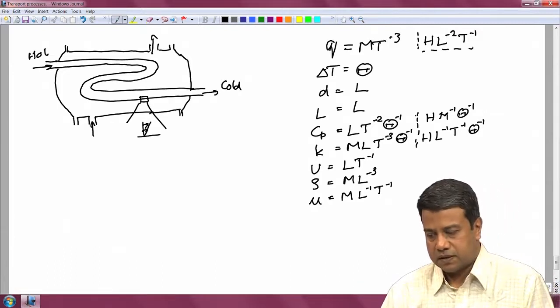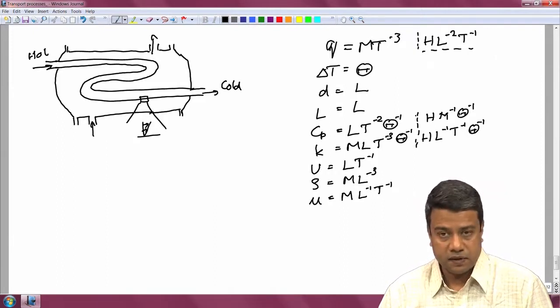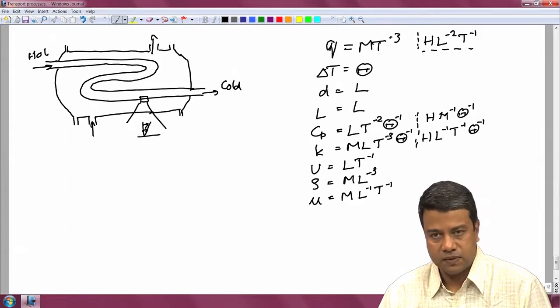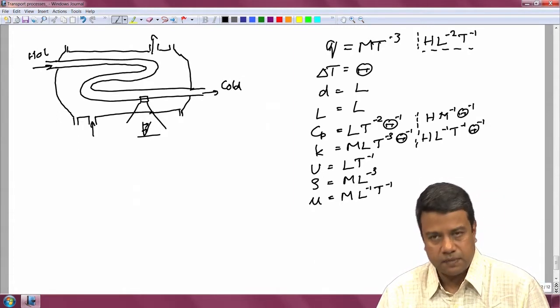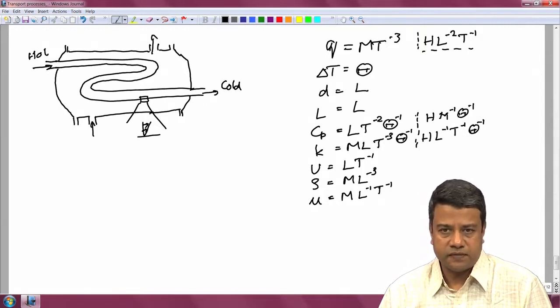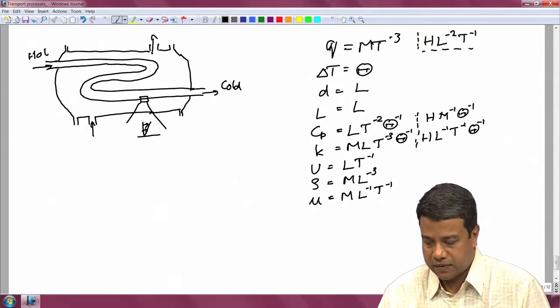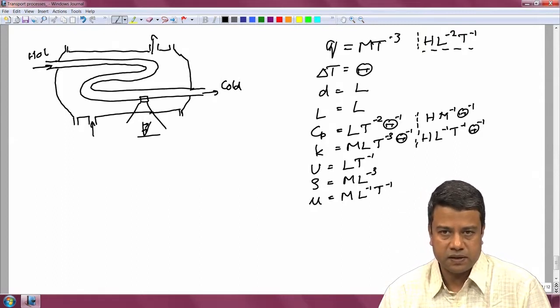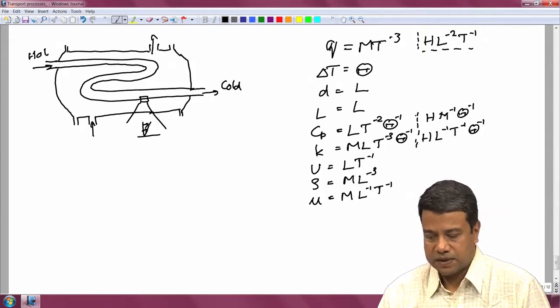It involves the dimension of thermal energy, and that can be cancelled only against one of the other thermal energy dimensions in this problem: either the specific heat or the thermal conductivity. The specific heat involves the mass dimension as well, so you would have to bring in one of the mechanical quantities. Using the thermal conductivity is simpler because it does not involve the mass dimension.